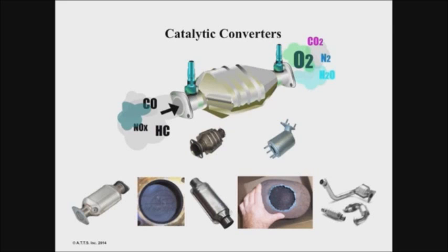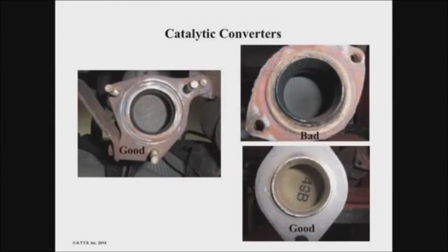You could look at different things and think. I took a couple of pictures here of a brand new catalytic converter. The substrate you can see looks nice and clean. A bad one up top, you say, why is that one bad? Well, of course, we tested it. This thing had 180,000 miles on it, okay? And this one also had 180,000 miles on it, the front converter. And you can see the one that says it's good up top, the old looking one, that thing still was very efficient. It was just the second cat that really took a hit.